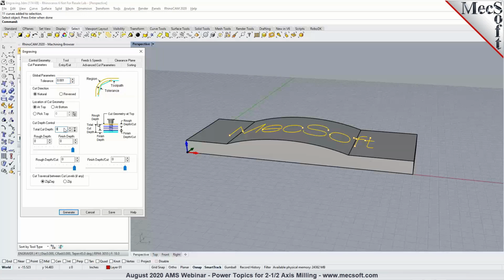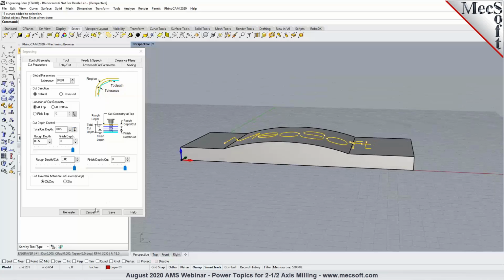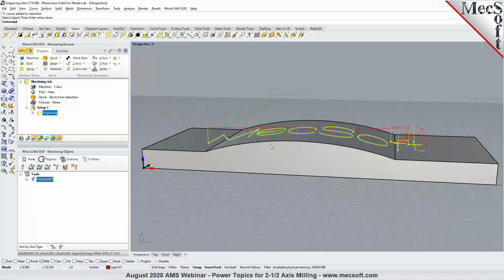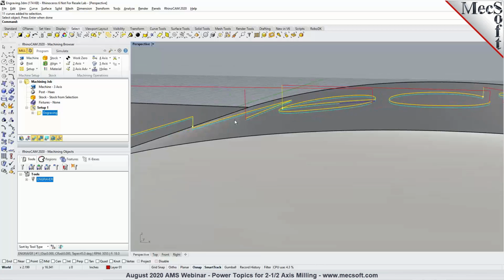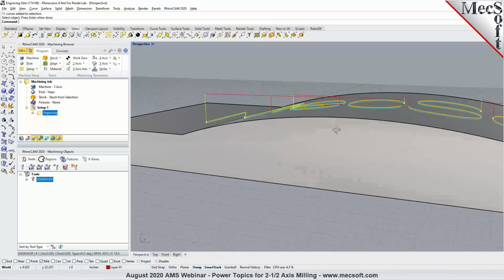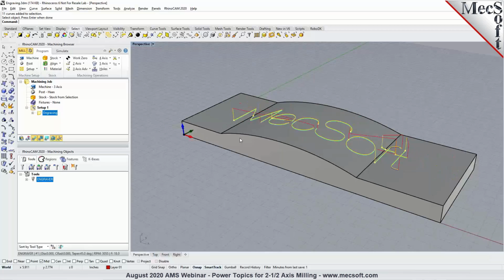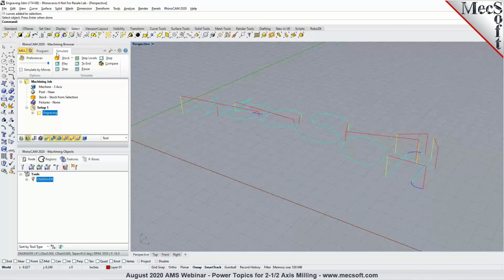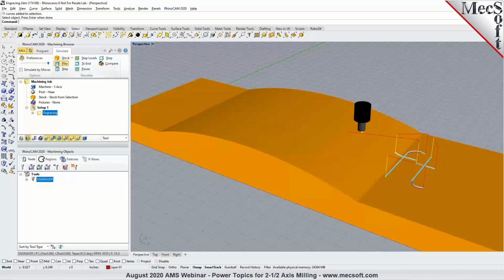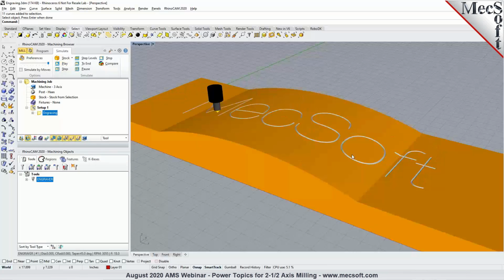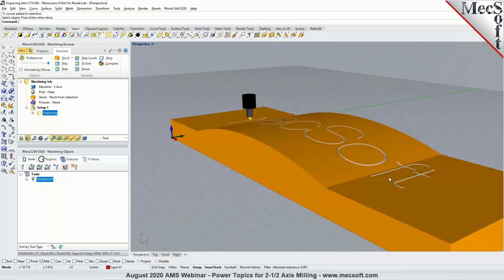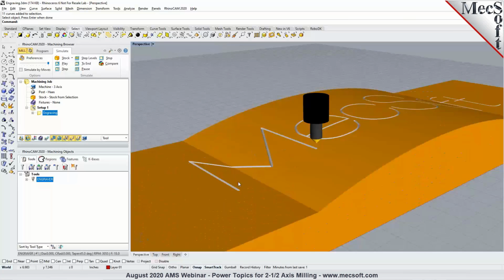And now when I specify a total cut depth in here, so I'm going to do a 50 thousandths depth, similar to what we did before. So it's going to maintain the same depth across the 3D curve geometry that you have here on engraving. So as you can see, the toolpath stays on the drive geometry and also maintains the XYZ varies as it follows the 3D curve geometry. So it's not resulting in a planar toolpath. It does follow along the 3D geometry. So this could be one of the very nice use cases for engraving along sculpted surfaces as well.